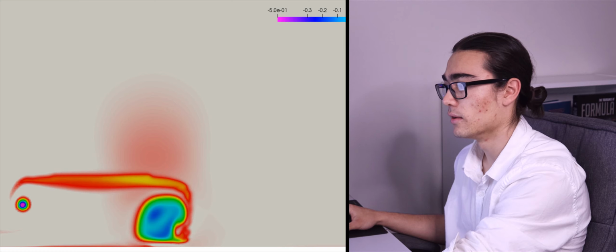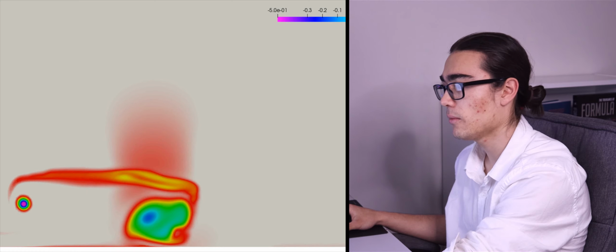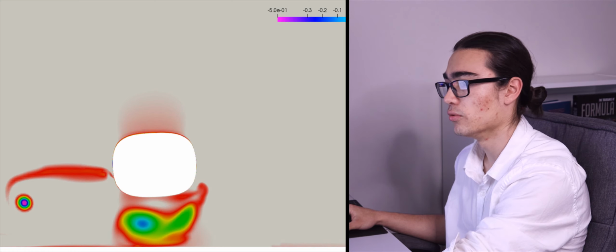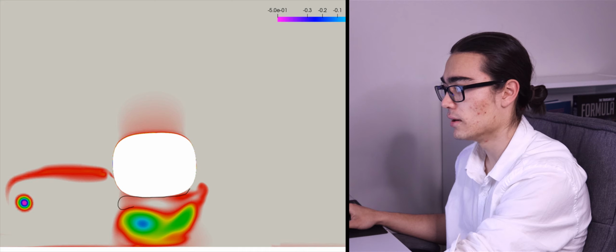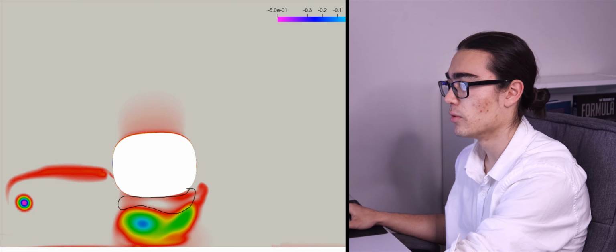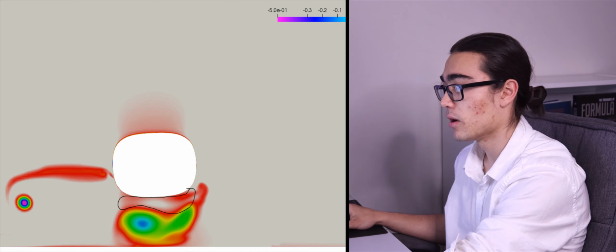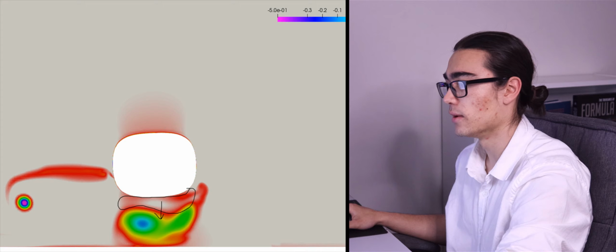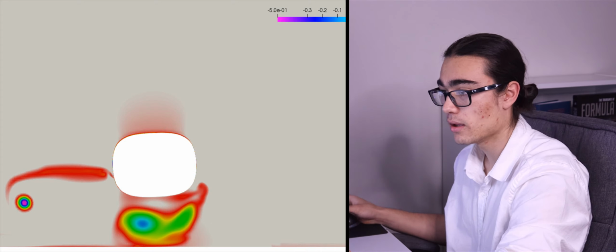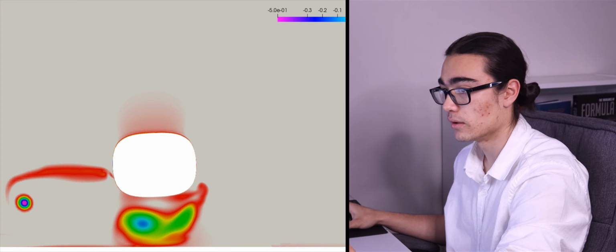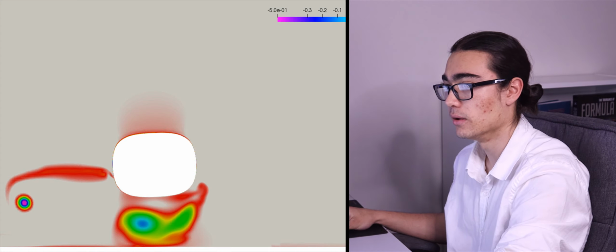And then we get into the interactions of the tyre here, and you'll notice in this case we've got a lot of clean high energy air here, and this is going to want to come down. The tyre is going to downwash it, and it's going to push a lot of this loss out the sides and squirt it out quite a lot, because we haven't pushed much air over the tyre. Because we're with quite a conservative wing, it's not actually that big.